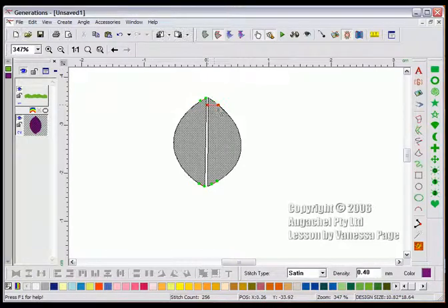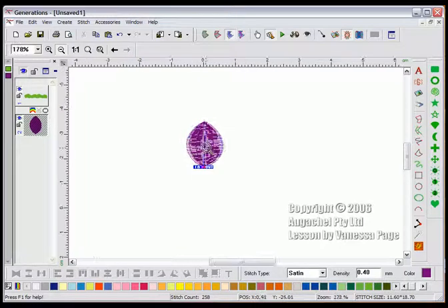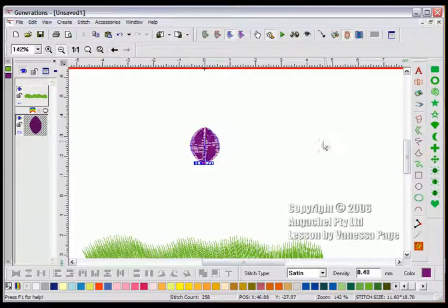So I'm going to drag it across so that it's straight there and straight across there, and I can do the same with the other one on the other side, just so that I make it straight. Hit enter, escape, and generate. Okay, that's looking a lot better. Now I'm going to zoom back out again, just so you can see the actual top of the grass.